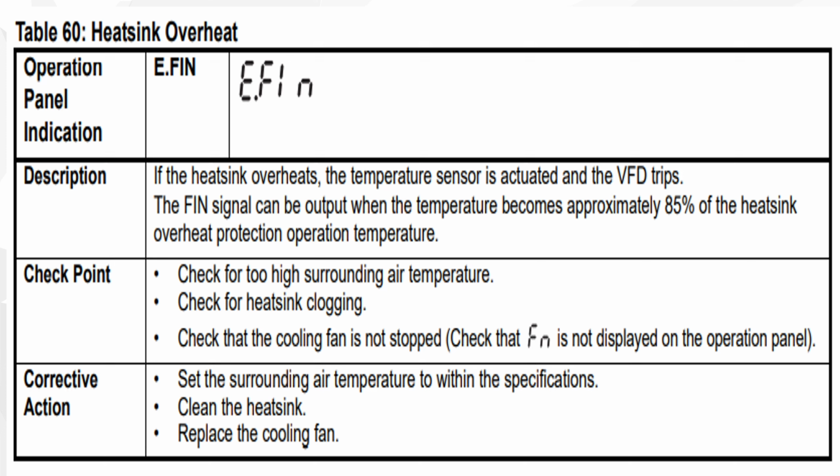If we see that the fan is not working, we can use an external fan to cool the VFD from inside. So we have a few steps. First we check what the issue is, and second we do the task, like replacement of the fan, cleaning the inside of the VFD, and changing the environment also. If there is too much temperature in the outside environment, it will increase the VFD temperature internally, and the heatsink also will not work. So we can resolve it like this.